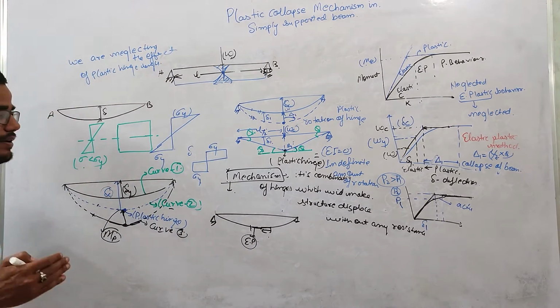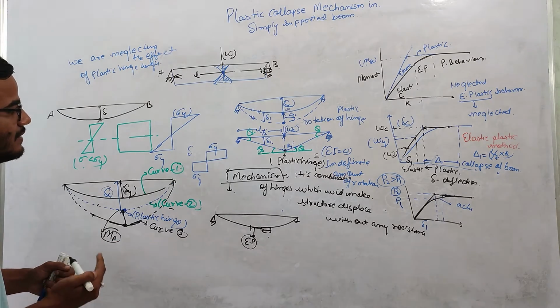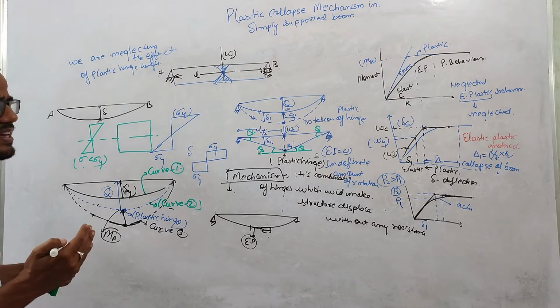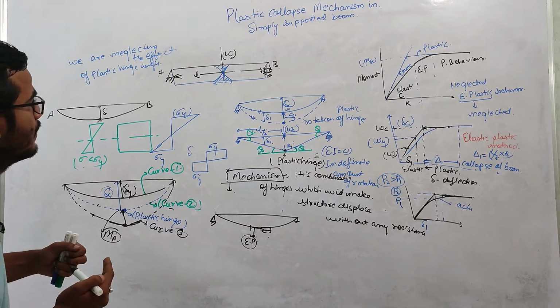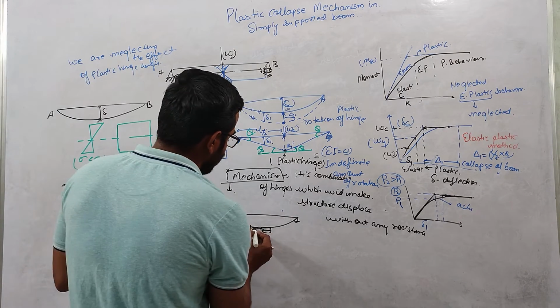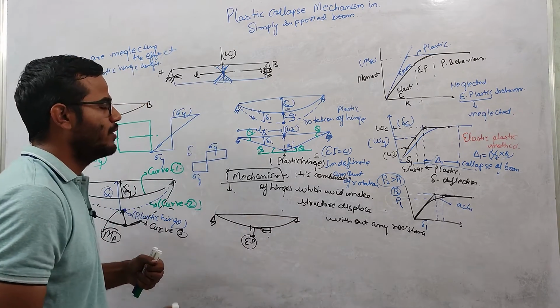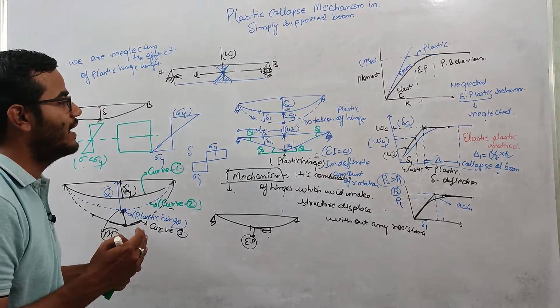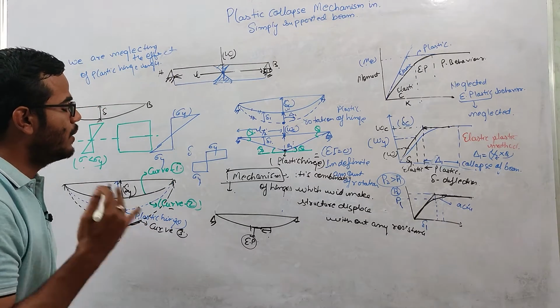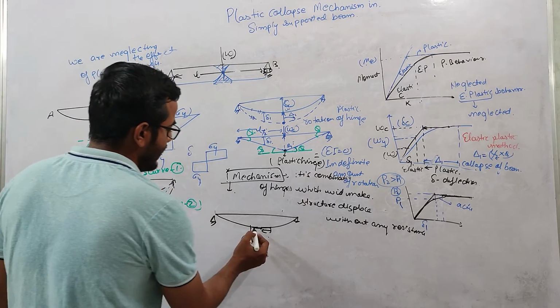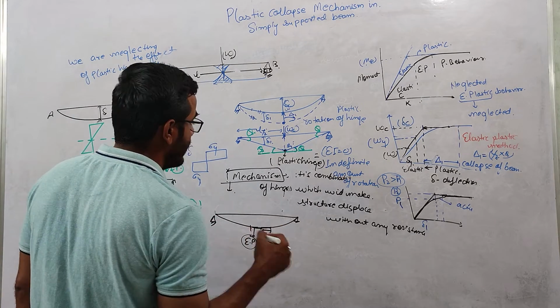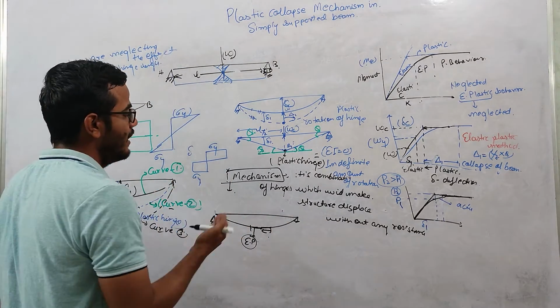Okay, and the length of this plastic hinge along this member is an important thing. If you want to have a detailed, accurate analysis, then you need to consider this variation also, the elastoplastic behavior across the cross section and along this member.